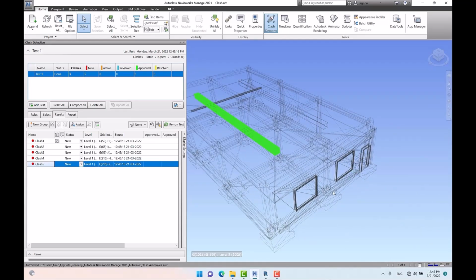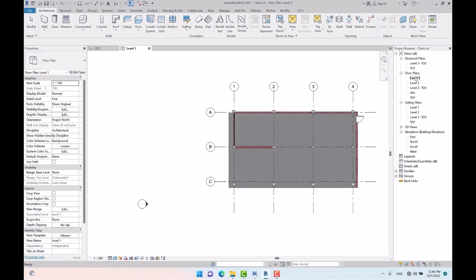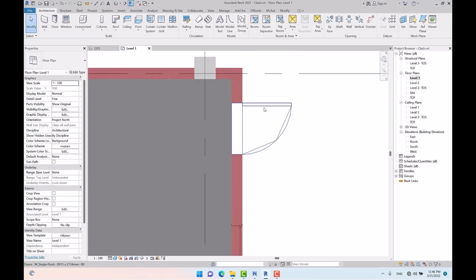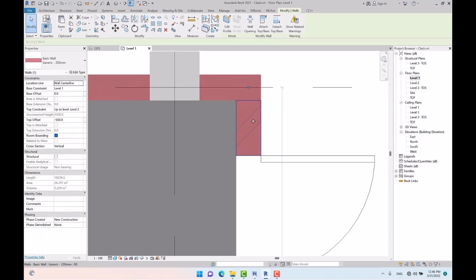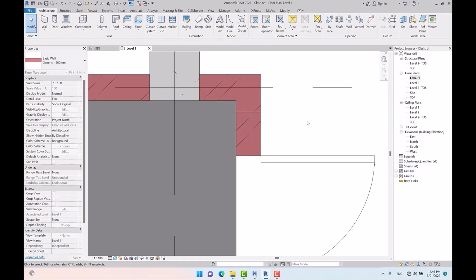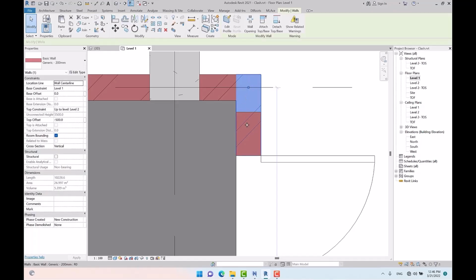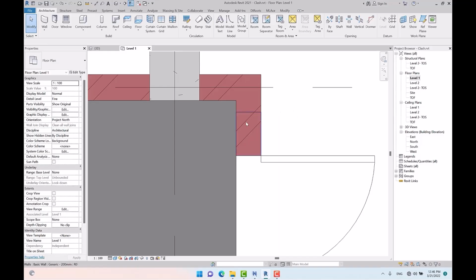But for now, the greatest clash which is not reported here is the wall here, which is not recognized as a clash, since we got 2 copied walls, because here there is a point. Actually, when you paste the walls aligned to the same place, their connection will be different to their lateral walls, so that these 2 walls are not recognized or not reported. But right now, to convey the message better, I want to show the connection between these 2 walls. I extend the wall downward. As you can see, the other one is extended to the end, but the second one is not extended, so this clash is not recognized as a duplication. So I consider this a weak point of Navis.